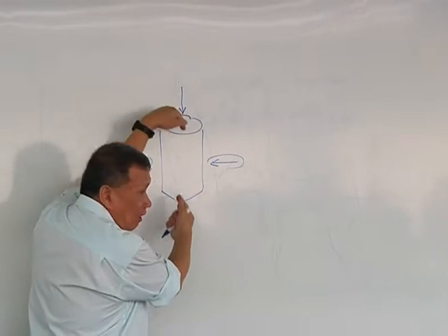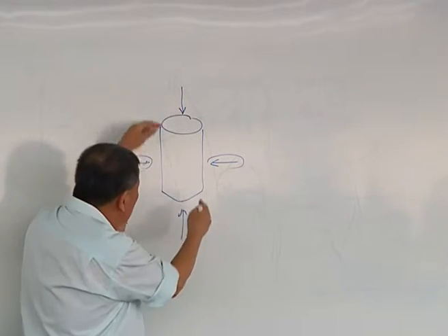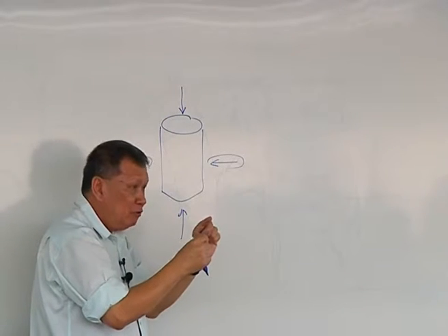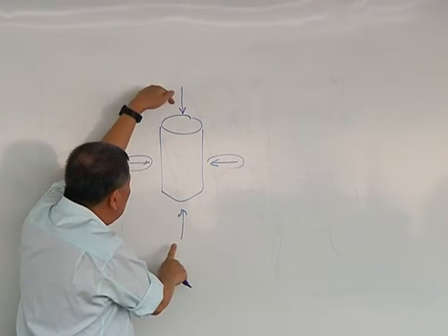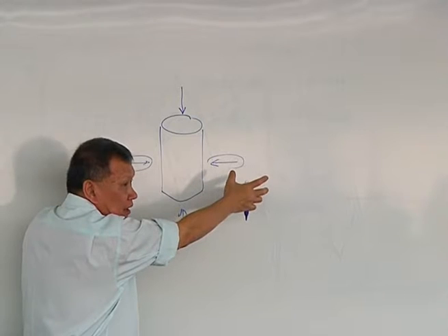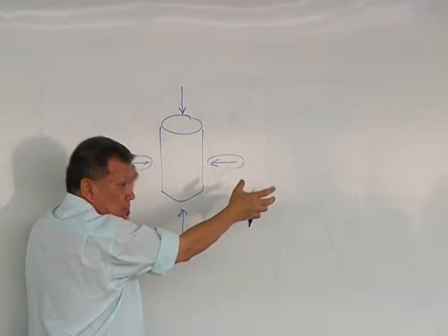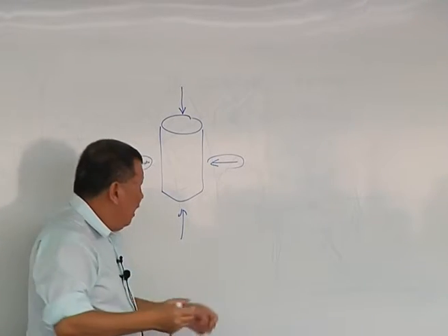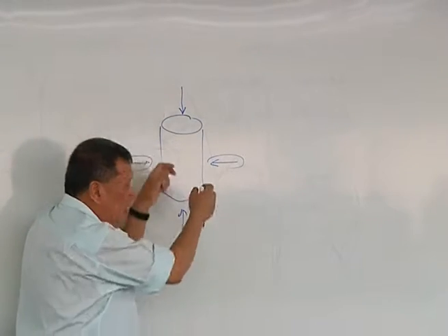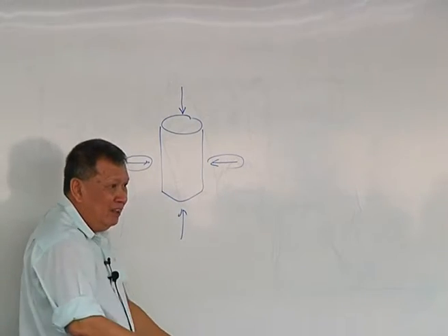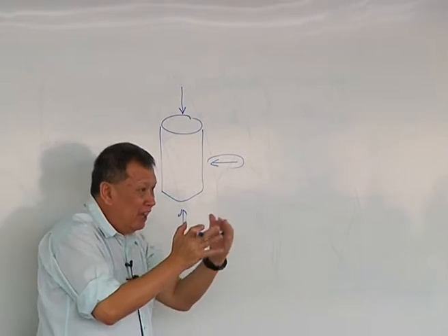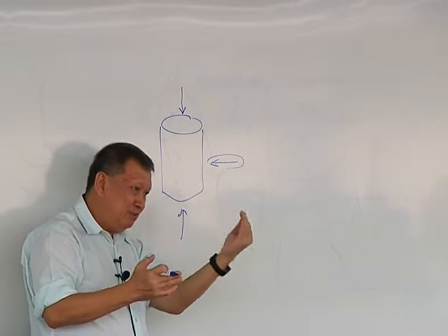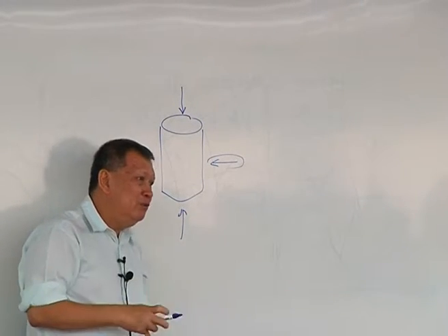And then you will keep going on. You keep loading past this particular stress level. You keep loading, it will still be elastic, but beyond a certain point, it will go outside. It will go outside because it's gone plastic in the other direction. So in one case, it's squeezing out like a toothpaste. In the other case, it's washing out this way. So in between, you get an elastic regime. So you are fluctuating between two plastic regimes, two yield conditions.